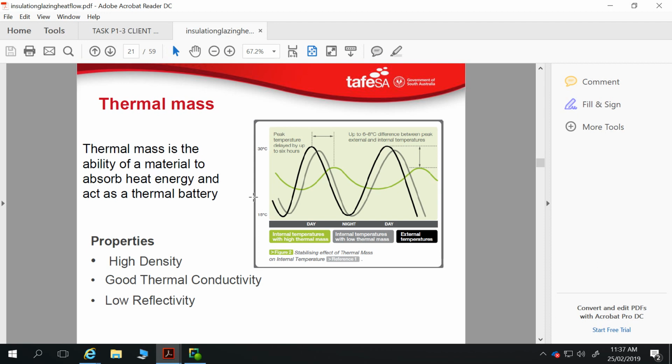Where thermal mass can be a real curse is weeks like the week we've got ahead of us now. It's like 37, 37, 37, 37, 38, 39, 40, 40. At the end of that, I know my house is going to be stinking hot. I've got an old cottage with walls about this thick. Nothing you can do about it. It will heat up. That thermal mass will be a curse at the end of this week. But if used appropriately, it can be of real benefit, and used judiciously.